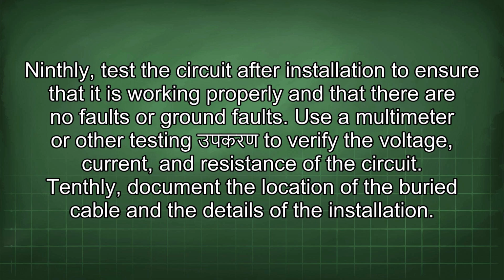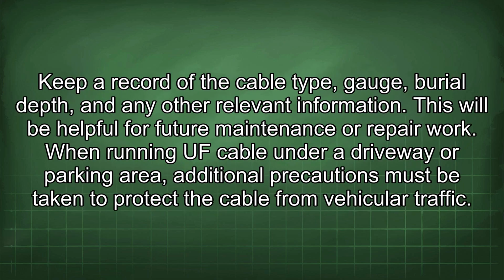Tenthly, document the location of the buried cable and the details of the installation. Keep a record of the cable type, gauge, burial depth, and any other relevant information. This will be helpful for future maintenance or repair work.